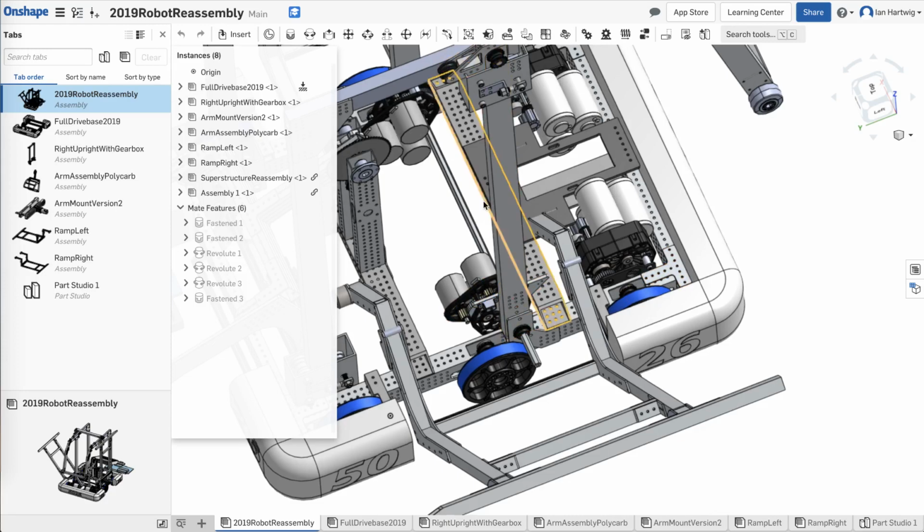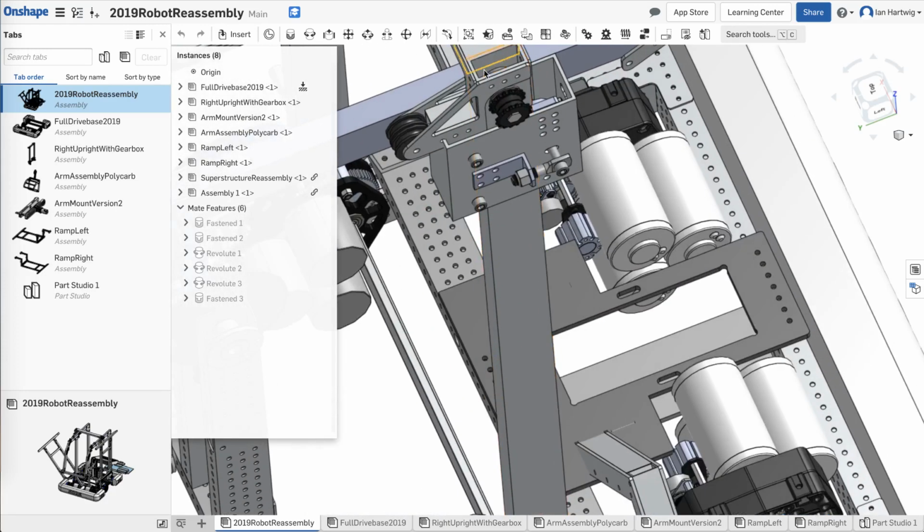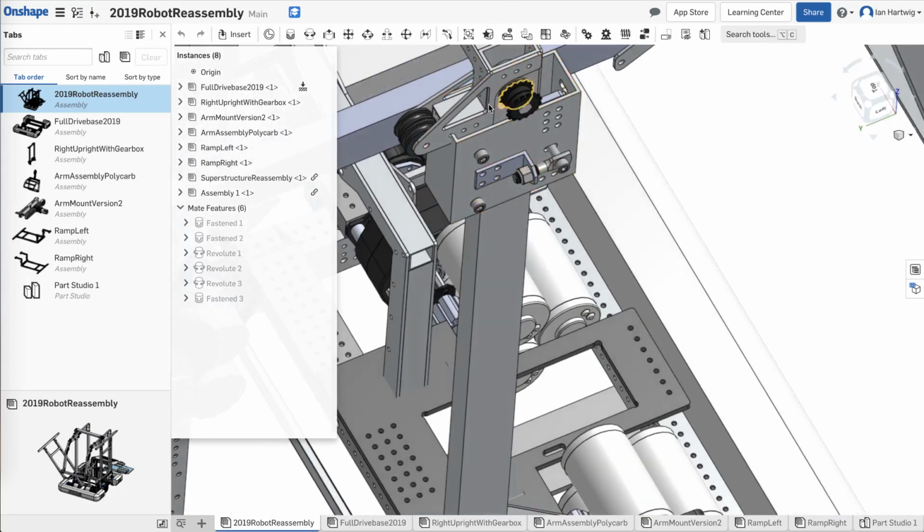So you can see that we make a lot of things out of these flat plates, like this one here that holds up the ramp pulleys. And I call it 2.5D because there's really only two dimensions of geometry that matter, and then the third dimension is just that the material stock is some height.